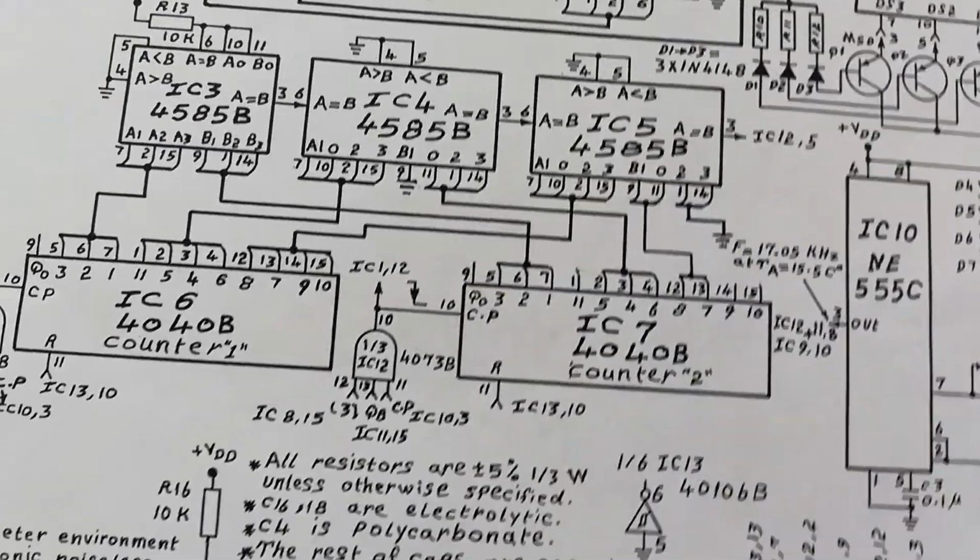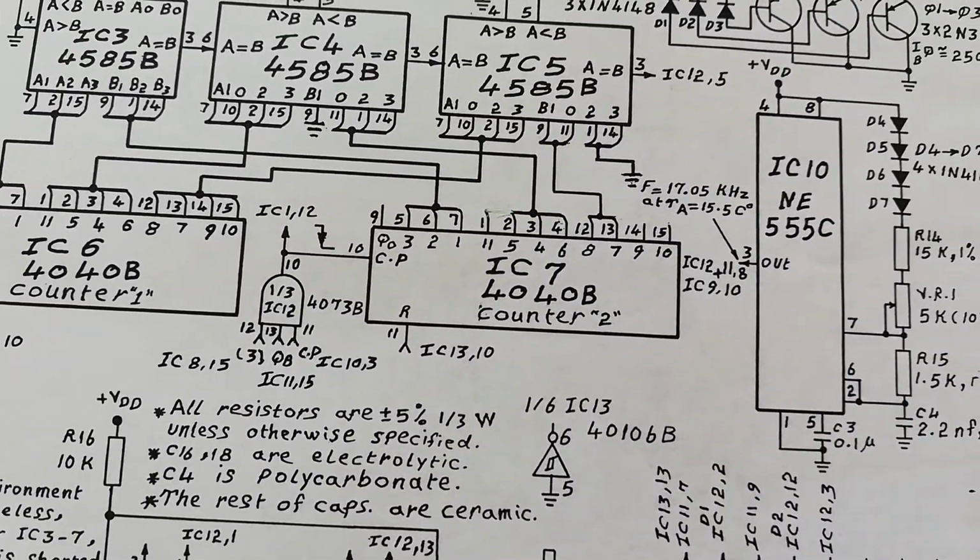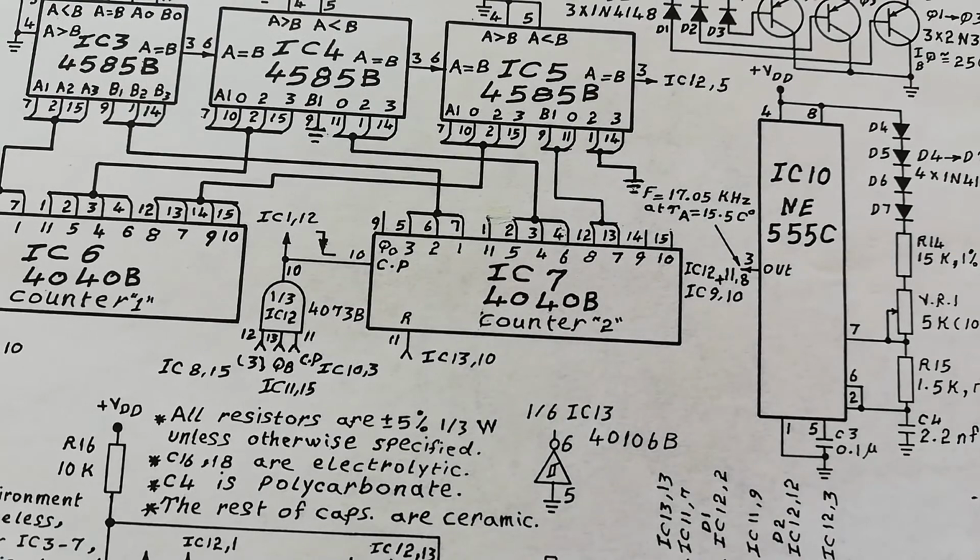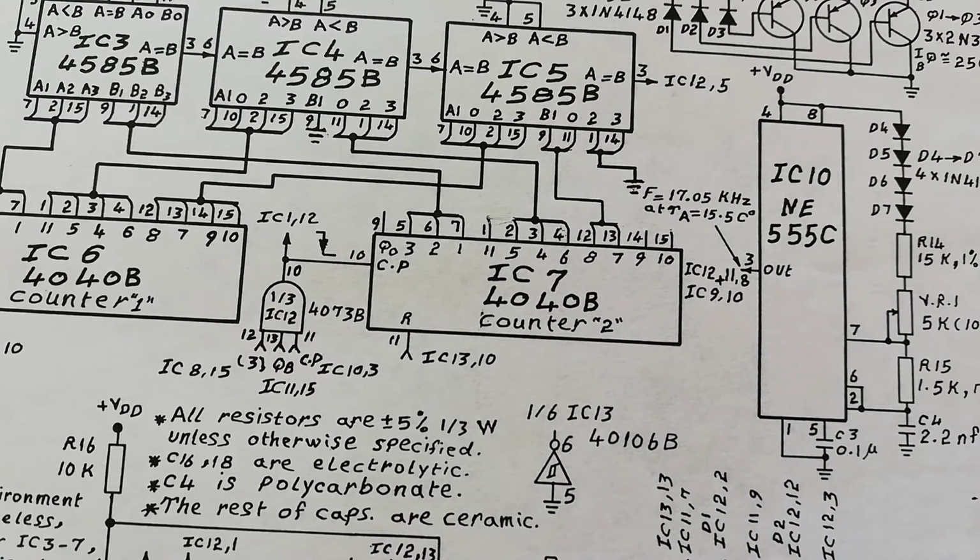And something else to add, that this chip must be installed in the transmitter, because after all you can't put the unit in a cool place where this chip is going to measure the room temperature, while the transmitter is located in a hot place.